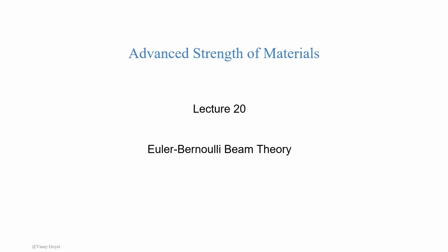Other applications consist of rocket engineering. So my area of expertise, it is possible to size a launch vehicle because the launch vehicle is very long. So think of a rocket, it's very long and slender. So it is possible to actually use beam theory to size some of the aspects of the design by looking at the angle of attack during flight, the Mach number, the drag coefficient, the lift coefficient, the thrust, the engine loading conditions, and the pressure inside the tanks. All that can be considered in a very simplified model using beams. And I may have the chance to go through one example so you can see how that looks, but it's possible that I may not have the bandwidth to cover that.